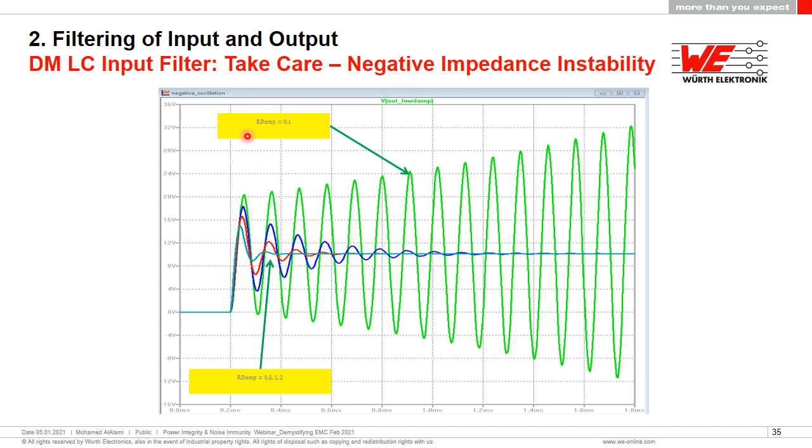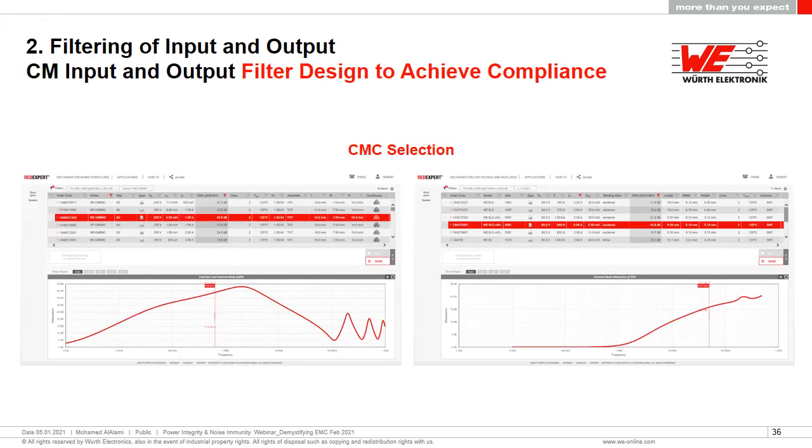So that damping of the aluminium electrolytic is sometimes a good thing to have as well. There is a whole other set of presentations that I've done that look at this in a bit more detail, and look at how we can calculate the damping requirements and how we can design the filter so that we avoid any issues with instability. But that's for another day. Okay, so that covers differential.